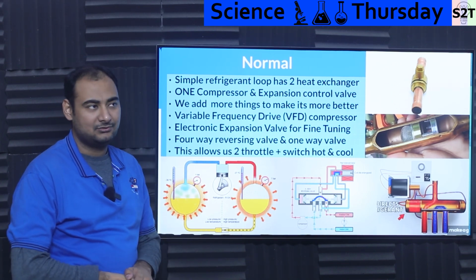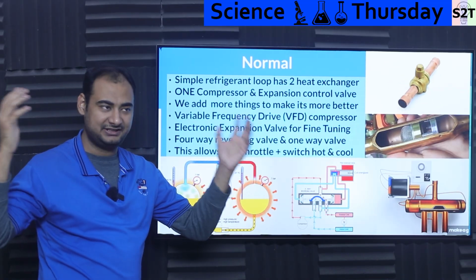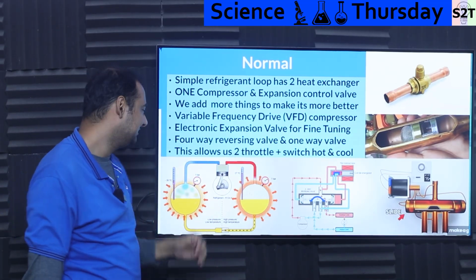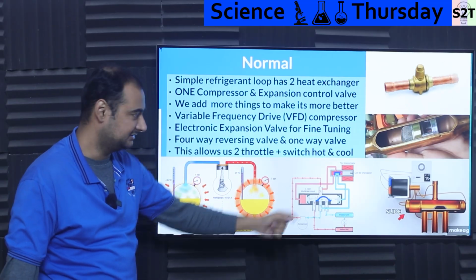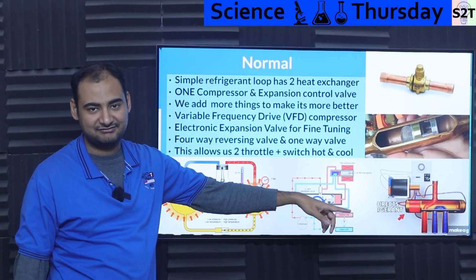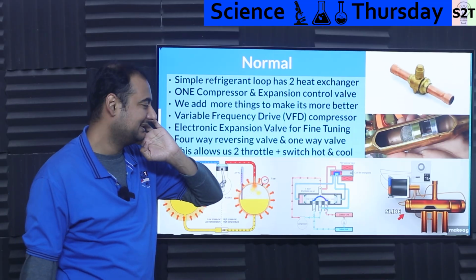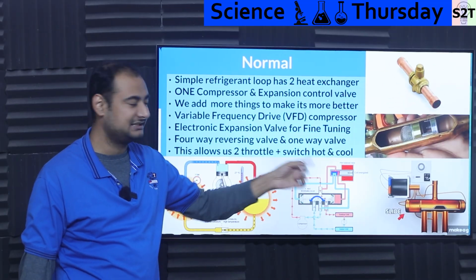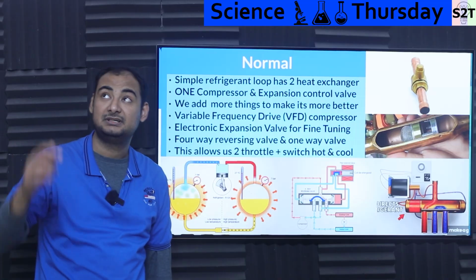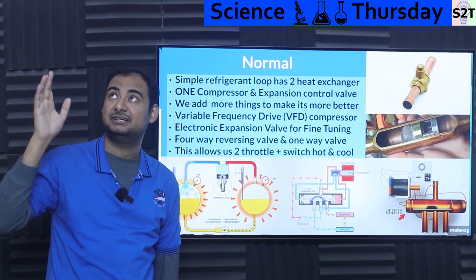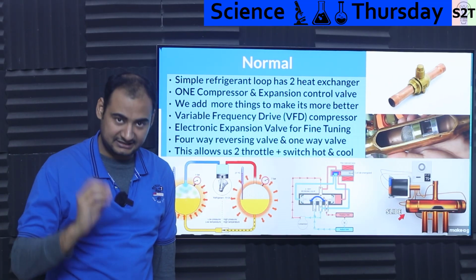Then somebody's like, hey, why not remove parts of the AC and then rotate it around for winter? What if you added a four-way reversing valve, this puppy? Now, this four-way reversing valve is very convoluted, and the primary penalty with this puppy is it will reduce your air conditioning efficiency. For example, when I bought this heat pump unit, Blue Star unit,